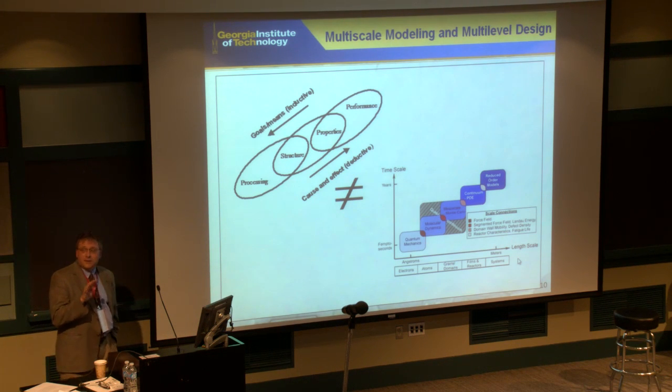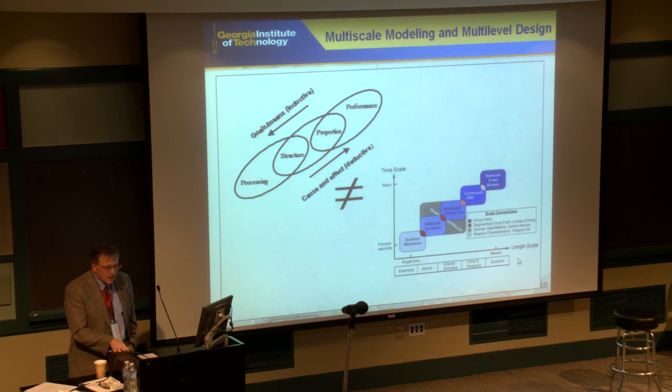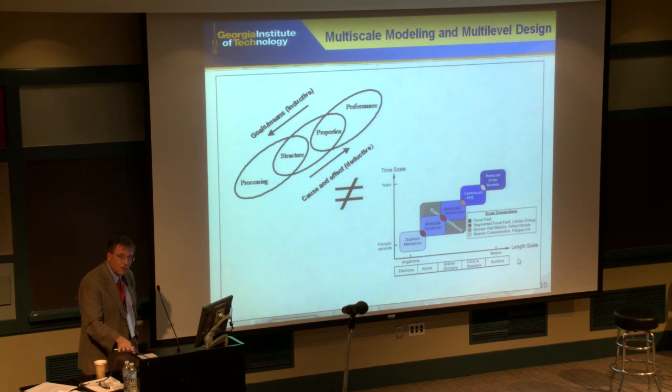This is another linchpin of the notion of the Materials Genome Initiative in ICME, that we need to get across the point in our university instruction and in our programs that multi-scale modeling is of two types, hierarchical and concurrent, and most often of hierarchical type, because the uncertainty associated with passing information among scales can actually swamp the problem. It's better to use scale-specific, high-integrity, high-confidence models rather than mixing it in with scale-bridging uncertainty, unless you have a good reason to do that, right?